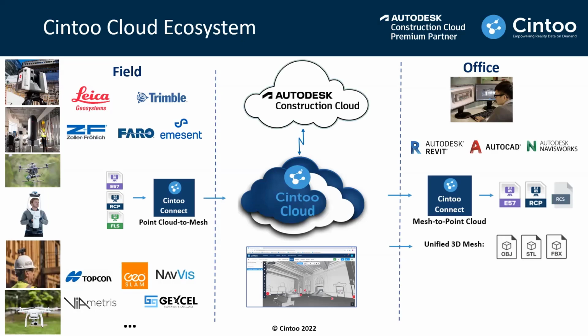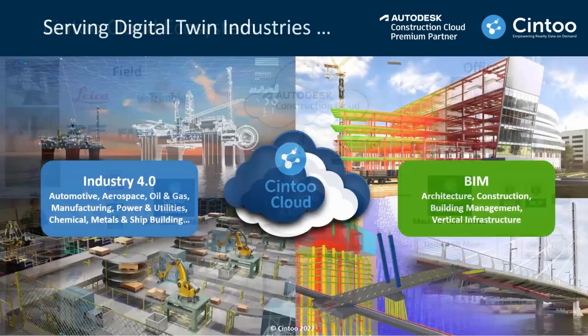And when it comes to connecting to Autodesk Construction Cloud, we do it cloud to cloud, of course, using the Forge platform. We would then pull models in various formats, being IFCs, Revit, Navisworks, DWG, JT files as well. This is where you compare your existing conditions, being the scan data, to the BIM model, and then eventually detect issues. Those issues can be pushed back to Autodesk Construction Cloud, or you can also export them as a PDF or BCF file, which means BIM collaboration format, or you can also share the viewer. So this is how it works.